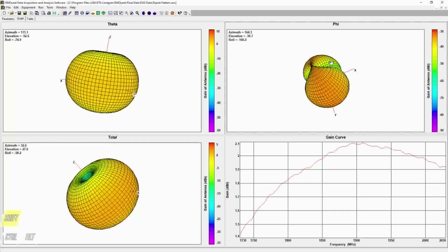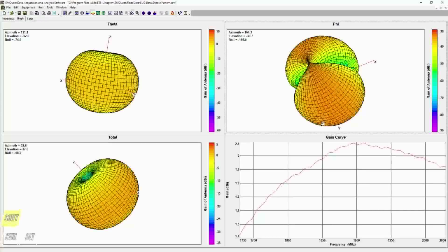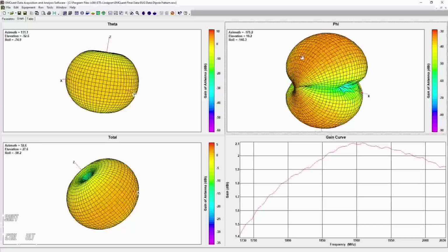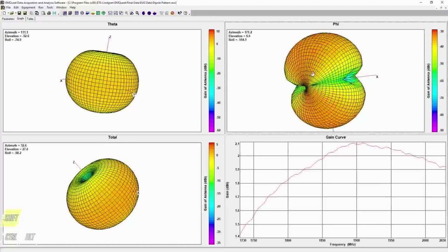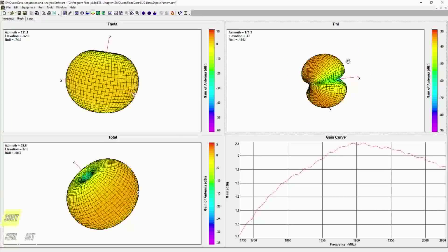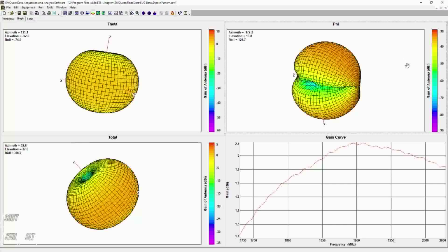And what the aspect ratio is, is kind of the divisor, how much of a depth of field you have, right? So it's the perspective view. And if you pull it out far enough, you end up with no perspective at all, the fact that front and back look the same, versus you can push it in until it's pretty distorted, which is probably not what you want either. So the default aspect ratio is a 5, and so we'll put it back there. But that's all happening when I hold Shift and I drag.